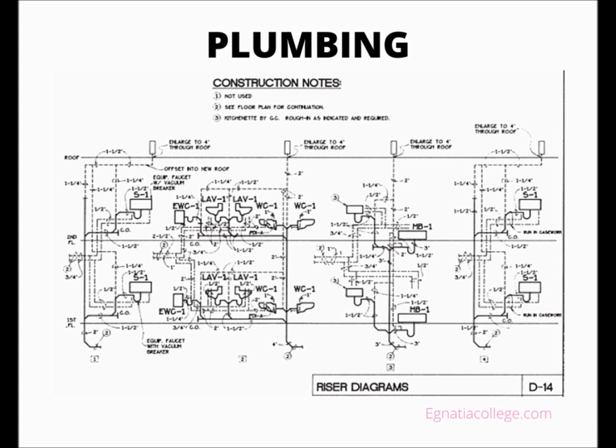The figure shows riser diagrams for the fixture connections in the school addition. A riser diagram shows the vertical arrangement of the piping. Notice that there is no hot water return shown on these diagrams, because the return is connected to the supply before the supply reaches the first fixture.